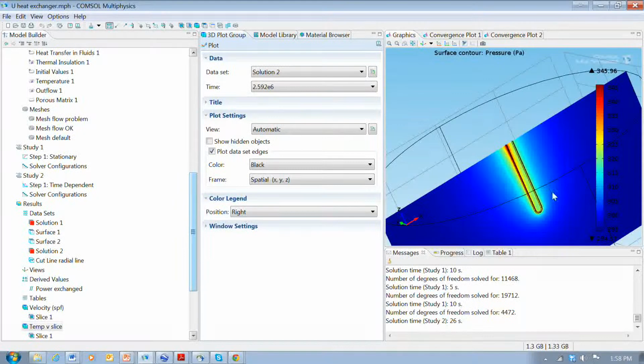So there's the temperature along this cross section, and I think you have an interesting effect where what might happen is that the fluid goes down here and sheds the heat out into the formation, and then coming back up, it looks like what could happen is the fluid could actually heat up as it comes back up here, because right here most of this is going to be the hottest point, and so as this heat conducts over here, I think that's what would happen if we were to actually look at the temperature along this profile.